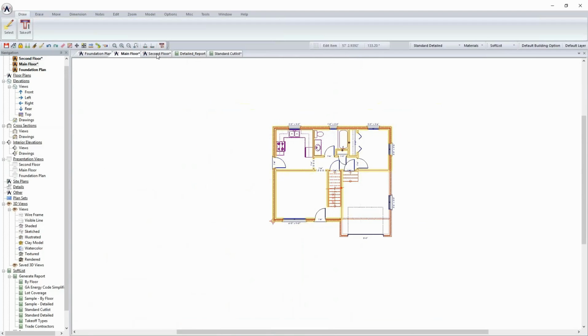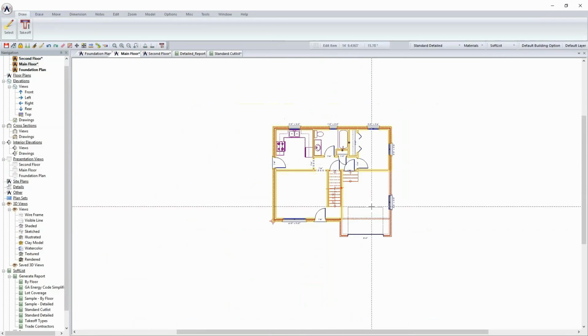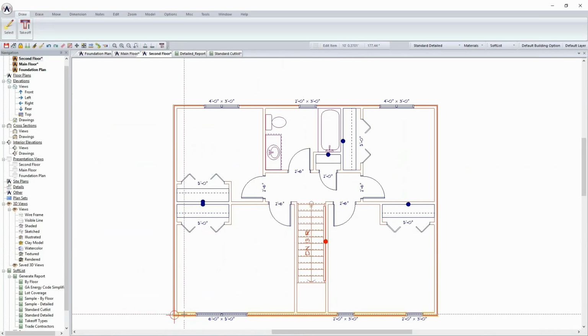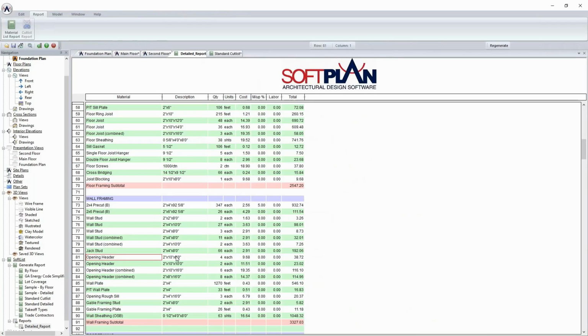In the case of the pre-cuts, obviously it's everything as far as the wall is concerned on the second story and everything minus the garage on the first story. Again, from the plan, if I right-click and highlight headers, it's going to take me back to the floor plan, and the headers across the front wall here are where my calculation is coming from, and the same thing on the second story. That's how this report came up with the 2 by 10, 8 foot, and that means the other headers shown on the plan are being used in a different area.